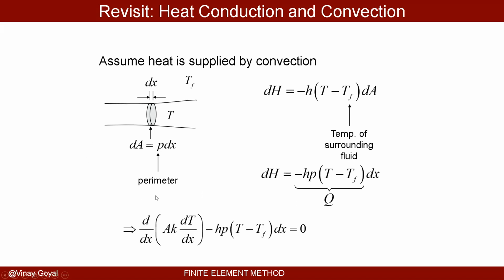Remember how the equations of equilibrium for the heat transfer problem are given by this. To recall, K is the conductivity of the material, A is the cross-sectional area, T is the temperature, H is the heat transfer coefficient that tells you how effective you are at losing or gaining heat through the medium. So you're soaking that structure in cold or hot air, for example, or hot or cold water. That H tells you how effective you are at transferring heat from the medium to the wall.